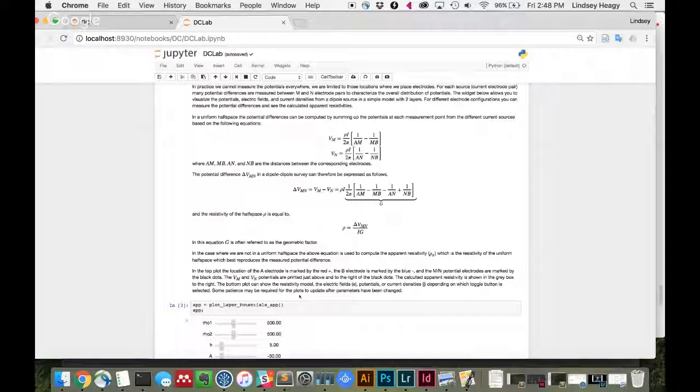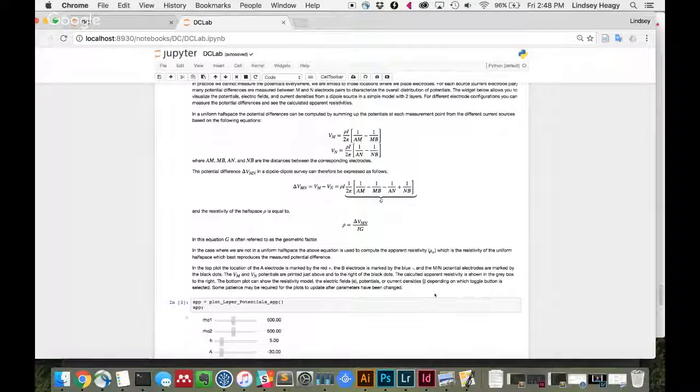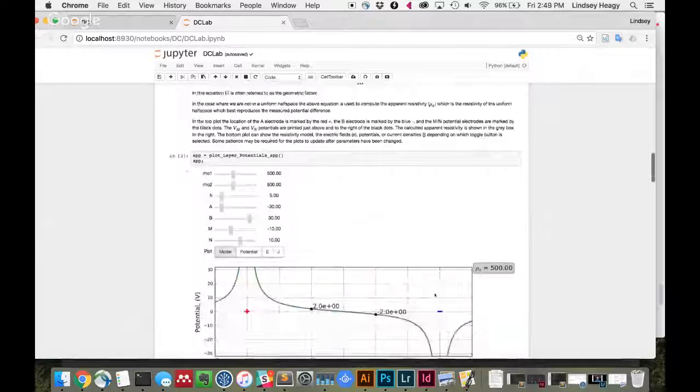Unfortunately, if I measure, you'll know what happens. If you take your little voltmeter and you just put one end into a battery, you can't get any reading. You need to make a potential difference. So what we'll do here is have the other end of the potential electrode be like this. And now here we're going to measure the voltage.